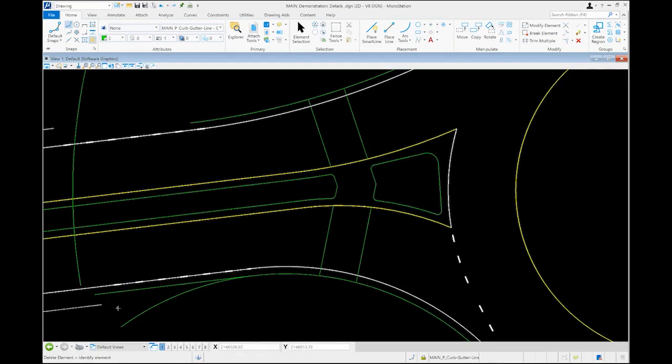Another option would be to provide a ramp at the end of the paved shoulder that would allow for cyclists to instead go up onto a shared path along the roadside. That is an option for single lane roundabouts. For 2-lane roundabouts, a bike ramp is a typical item to include in the design. But for single lane configurations, definitely consult with the project team and have that be part of the discussion about how we're accommodating cyclists and various trade-offs based upon the site context.